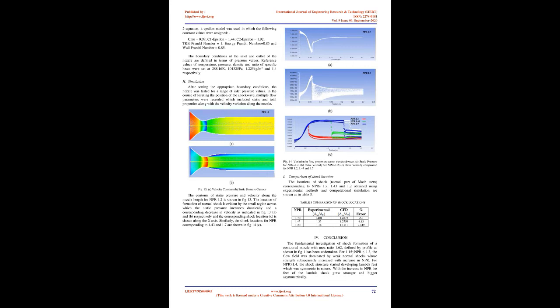The mesh structure used in the nozzle profile is of the map face meshing using a triangle, best fit, pattern, as it provides for a finer and denser packing of the grid within the limits of the geometrical boundaries. The generated mesh packs a denser fit within the throat section, which is the region of primary interest. Details of the meshing parameters and the generated mesh on the nozzle profile are shown in Table 2 and Fig 12 respectively. Fig 12. Mesh generation.